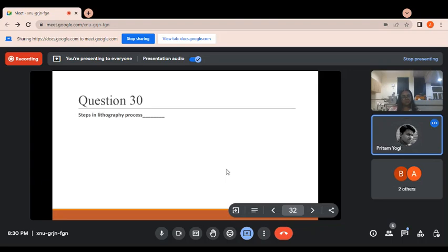Okay. And what is the main difference between the photolithography process for negative and for positive photoresist? Yeah, I remember a little bit that the temperature differs during the soft bake and hard bake. The temperature I think is 65 degrees centigrade. Yes. And after the soft bake, then we go for the hard bake process for negative resist? Yes. After soft bake, directly the hard bake.